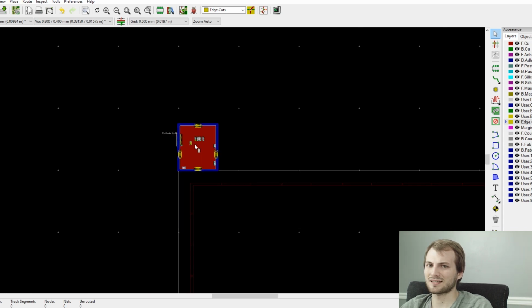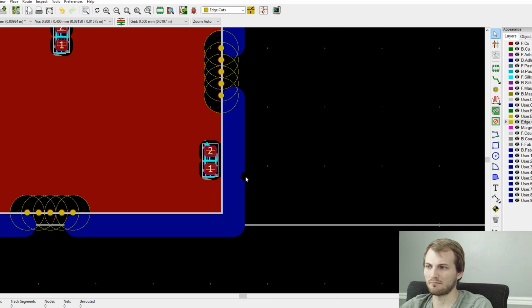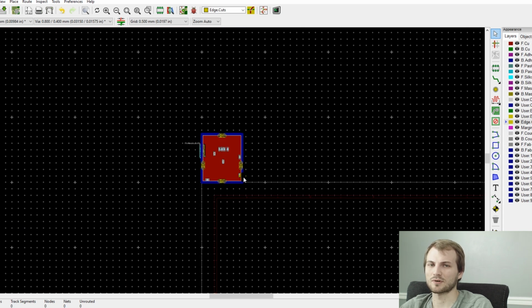And for this board, since it's pretty small, I'm going to go ahead and do a 4x2 panel with a 5mm gap per board, per where the router is, just to give the board a little more support so it doesn't bend. Most people will disagree with me on that, but since we have an assembly line, I really hate when boards are going in the reflow oven and they warp.